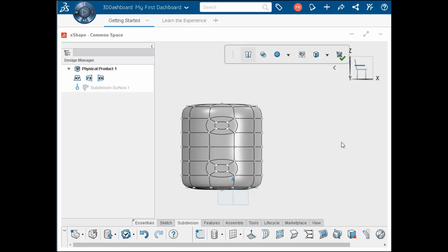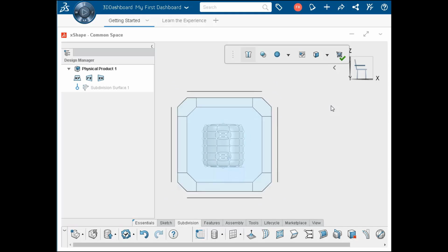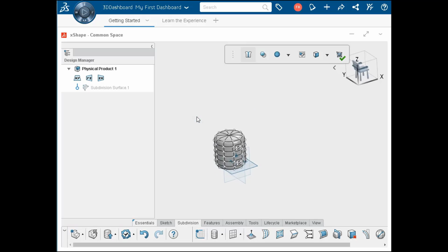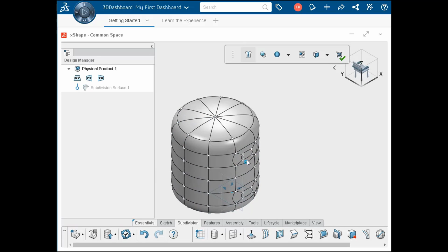I'd like an alternative to the standard isometric view, one where I can see the subdivided faces, so I'll press space and click the corner of the view cube. I'll select a face and use the Context toolbar to extrude face. The face is extruded and the tool is shut off after that one step. If we repeat this for the second face, we end up with a pair of extrudes to start forming the connection of our handle at the main body.